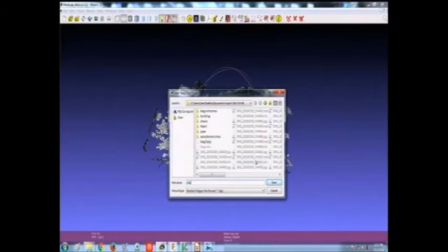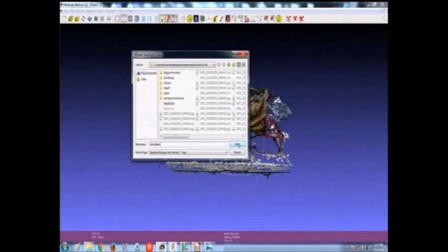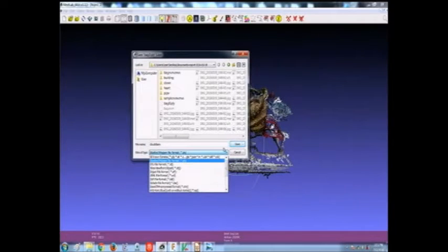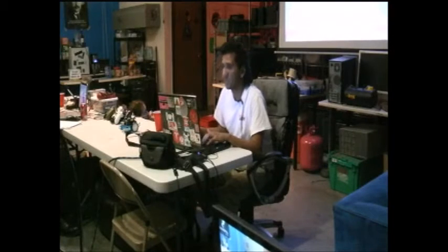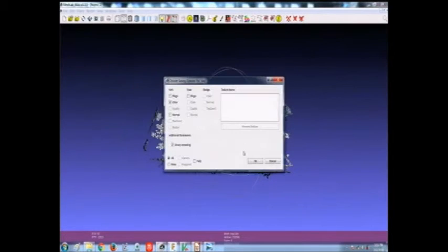So just be aware. So I'm going to save this file out as just a point cloud at the moment. If I zoom in, you'll see that there's nothing connecting all those dots together. And like I was saying earlier, there's 3 overlapping file types, which all sort of work similarly when you're doing 3D point cloud reconstruction. Either the STL file format, which is the standard 3D printing file format, or you get PLY and OBJ, which are related. So we'll save this out as a PLY. That's just Meshlab's standard export file format.